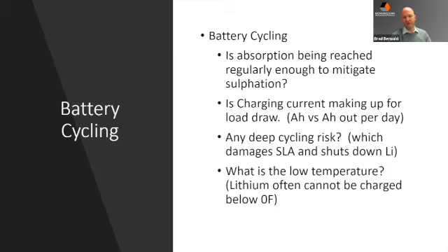And in the case of lithium batteries, while they can be cycled more, you still want to maintain a healthy low voltage disconnect point. Lithium batteries are a little more intelligent. They won't just get deep cycle damaged, but they may actually turn themselves off if they're taken too low, because they often have a disconnect built in internally. You definitely want to stay away from that, because that will take the whole system down. And proper design can allow you to mitigate the risk for that.